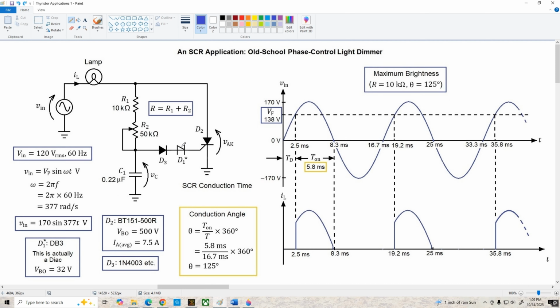So to make this behave like a 4-layer diode, I put a regular 1N4003 in series with it. That way it does break over in the forward direction, but it will not break over in the reverse direction.